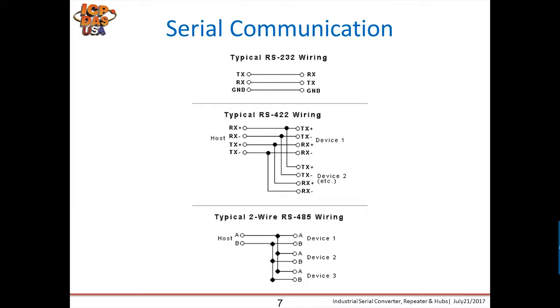Any of the slave devices on a RS485 bus can communicate with any other slave device without going through a master device. Both RS485 and RS422 have multi-drop capability, but RS485 allows up to 32 devices, and RS422 only has a limit of 10.